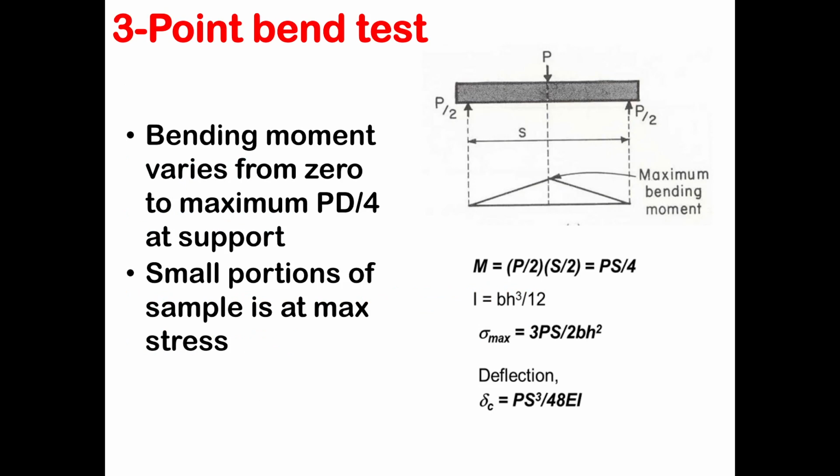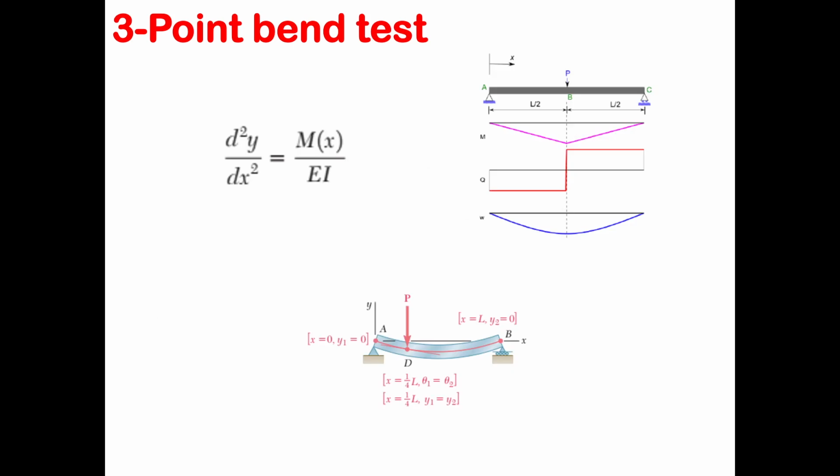For the type of test we have here, this is going to be your force distribution. This is going to be the moment for the pin supported beam. I'm going to provide all of these equations for you, all of the boundary conditions and everything. So you essentially have to apply this equation. You have to find the moment at the specific location you're looking at, find the deflection equation, find the maximum deflection, and essentially find the final equation. Keep in mind that you have already measured the maximum deflection. That was the idea. You should have measured the maximum deflection. But yeah, that's it for the bending test.